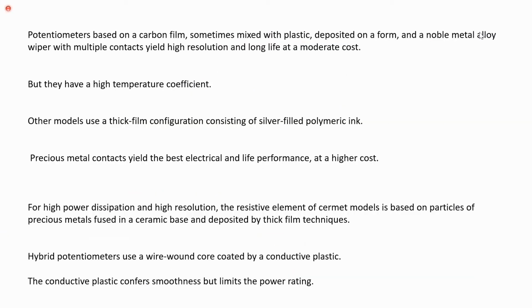Potentiometers based on a carbon film, sometimes mixed with plastic, deposited on a form, and a noble metal alloy wiper with multiple contacts yield high resolution and long life at a moderate cost. But they have a high temperature coefficient. Other models use a thick film configuration consisting of silver-filled polymeric ink. Precious metal contacts yield the best electrical and life performance at a higher cost.